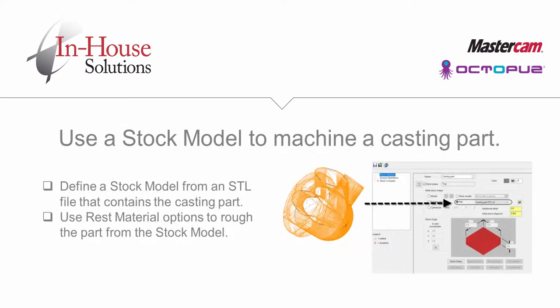Using a stock model to machine a casting part. We will define the stock model from an STL file that contains the casting part. Then you will use the same stock model in a REST roughing toolpath to instruct the software to remove only the stock material from the casting part.